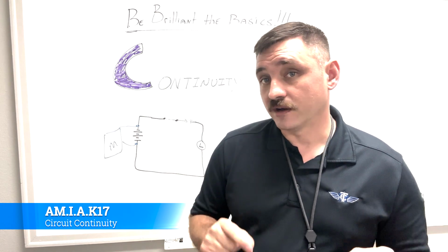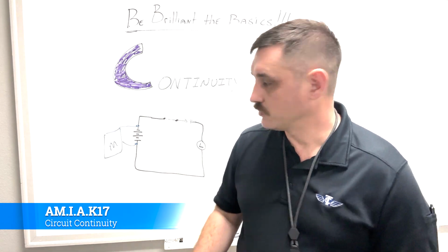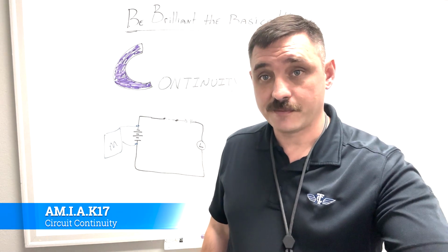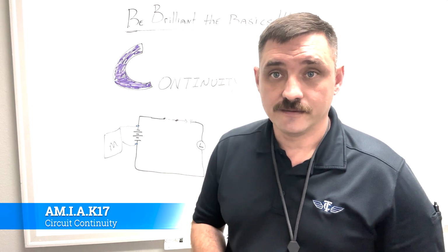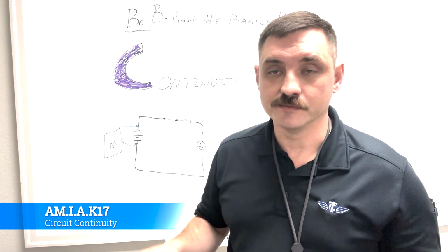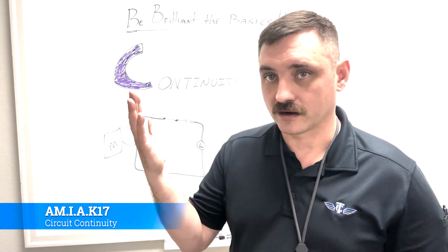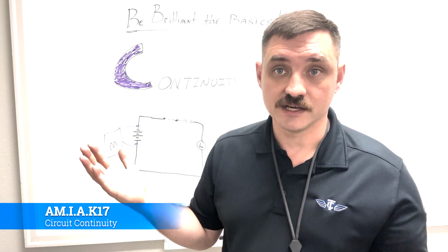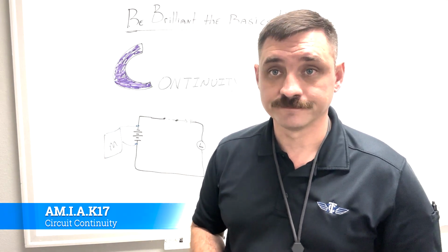But ultimately, you're going to find that through a variety of ways, and one of the main ways is through continuity checks. So that's what we're going to go do. We're going to give an example of a continuity check, and then in class, you're just going to do a bunch of them, so that you're very familiar with taking the wiring diagram and working with a buddy to troubleshoot where these discontinuities on the aircraft are.